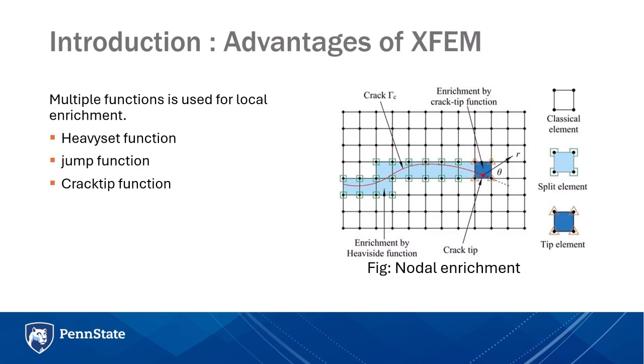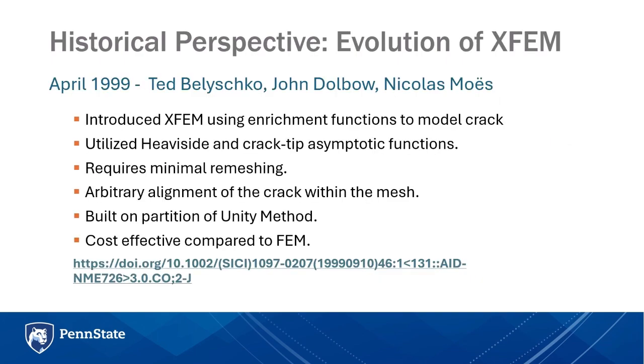Now, if we look back to the historical perspective of XFEM, the first major work was done in April 1999. It introduced XFEM using enrichment functions to model cracks, utilizing the Heaviside and crack tip asymptotic functions. It requires minimal remeshing. Arbitrary alignment of the crack within the mesh is allowed. It is cost effective compared to FEM.